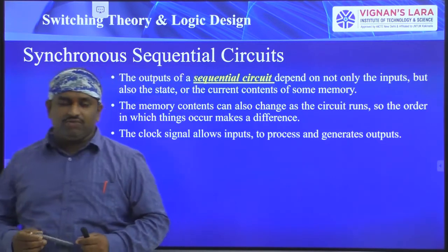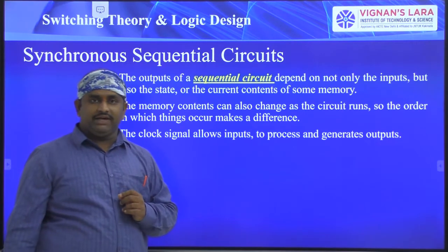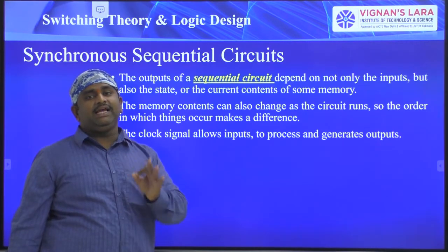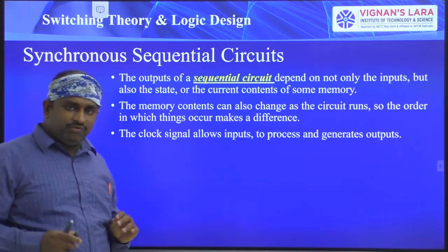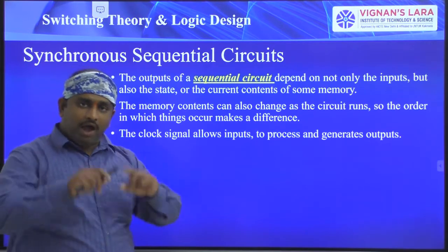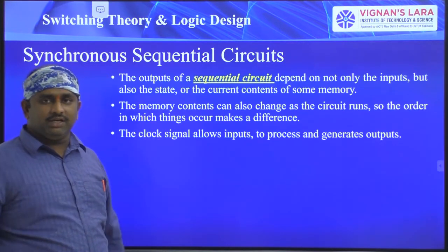So the synchronous sequential circuits we can define with a small definition, that is, all the circuit elements are controlled by a single clock pulse. In these synchronous sequential circuits we have a group of flip-flops. All the flip-flops are controlled by a single clock signal. That is called synchronous circuits.